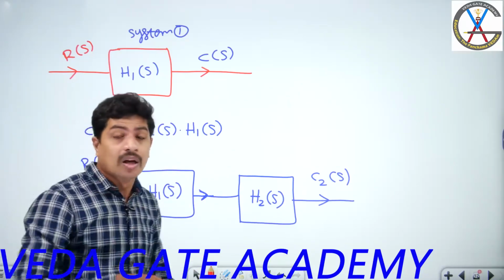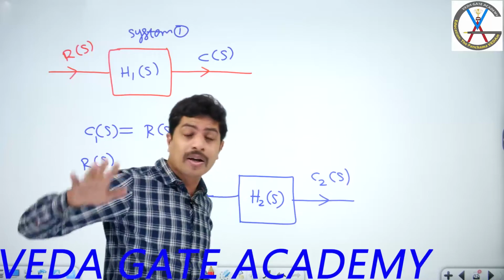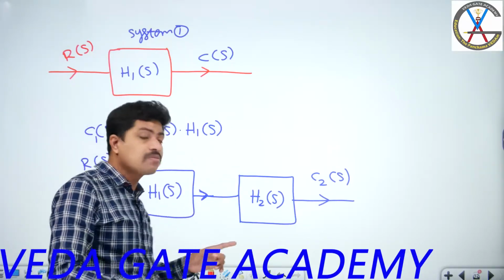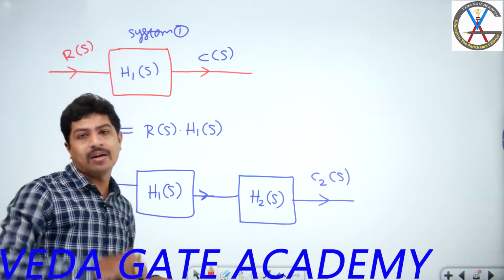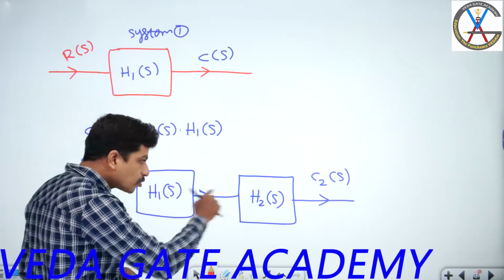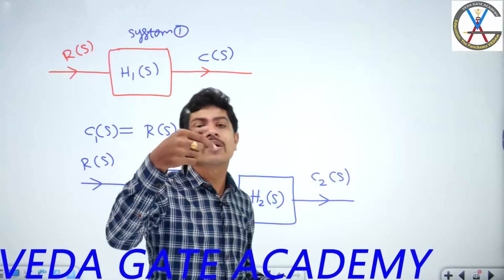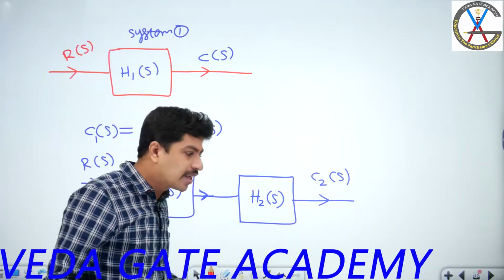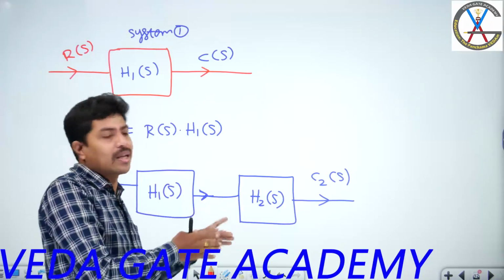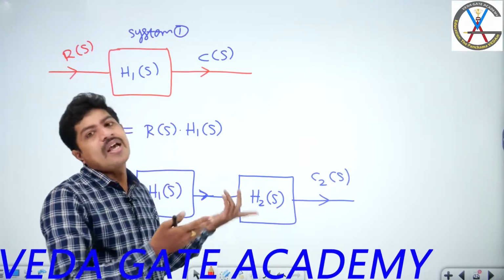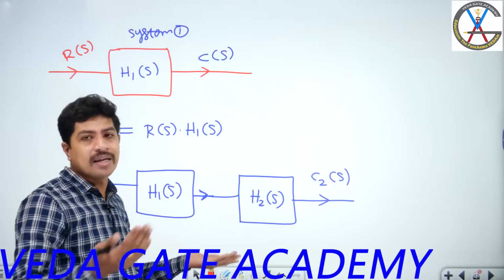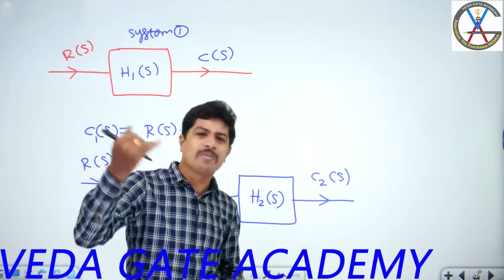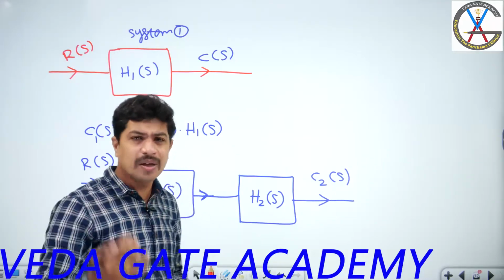One very important note point here is, in control systems, loading effect is not taken into consideration. It means we are not neglecting loading effect, we are just not taking it into consideration. Why? Because between every two systems, definitely there will be a buffer, which we are not showing. It is not required, because the buffer is doing nothing. It just maintains the same signal without this H2 and with this H2. Yes or not? So its gain is anyhow 1. We saw previously that the voltage gain of the buffer is 1. If you take an ideal current buffer, the current gain is going to be 1.